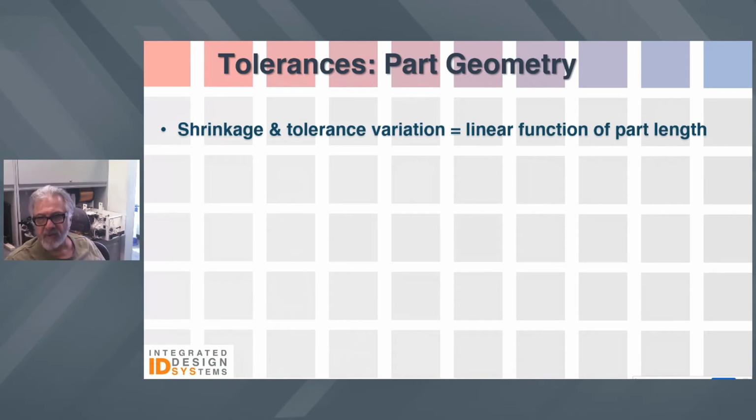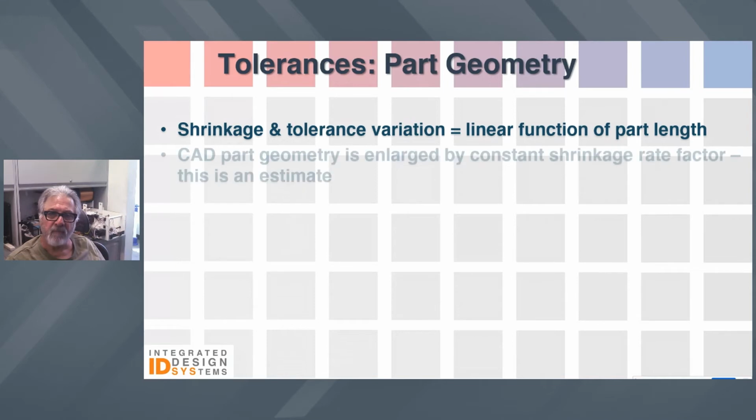So the tolerances are typically defined for plastics as plus or minus X number of inches per inch or X number of millimeters per millimeter. And that has to be considered during your design, the clearances you provide in your parts and the fits that you're expecting from part to part. In addition to the size of the part,